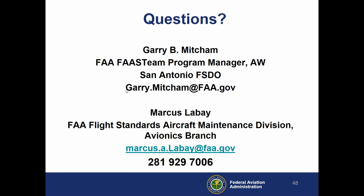If the airplane is sitting on the ramp with its ADS-B system on, transmitting its proper position and the altitude at the ramp that it's sitting on, that is not hazardously misleading information. That's accurate position information. The hazardously misleading information occurs when we change the static system and elevate the altitude of the aircraft to where it's now transmitting false information.